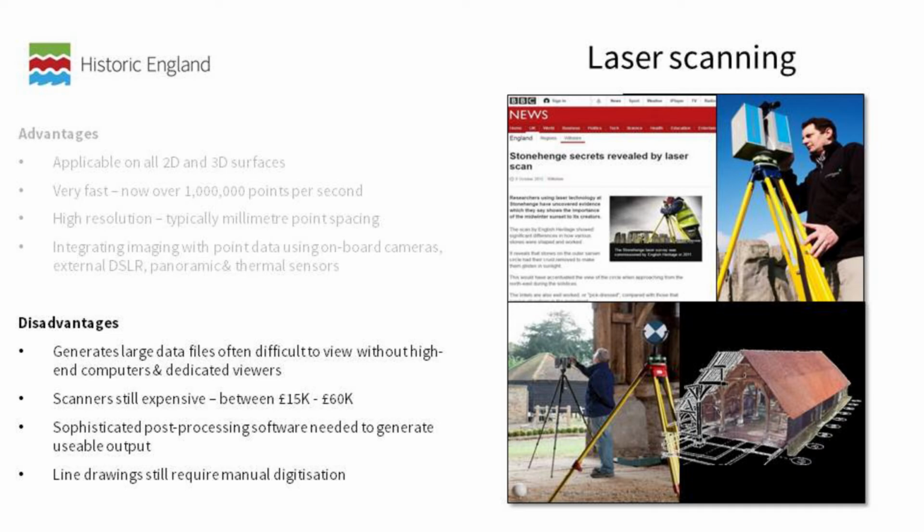And then when it comes to disseminating the results, you still have to either compromise the resolution of the data, or the end user needs a fairly sophisticated computer. And as I always like to remind people, if you want a line drawing, that still at the moment requires manual intervention. There are systems that will extract lines from laser scan point clouds, but they tend to be a jumble of unstructured lines which need so much editing that you might as well have just drawn it from the beginning. Not applicable here, but there's systems that will extract things like cylinders and joints for process pipes and so on very effectively.